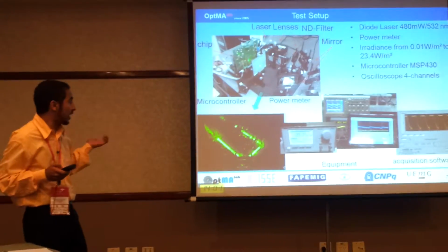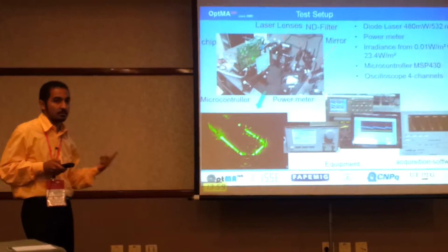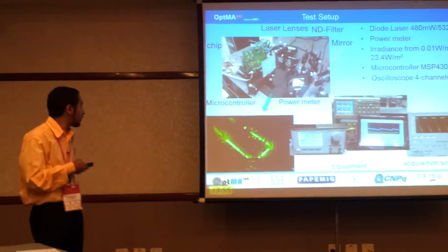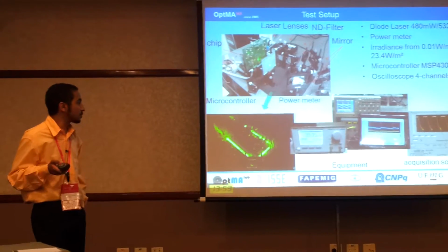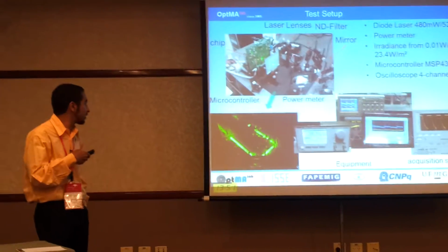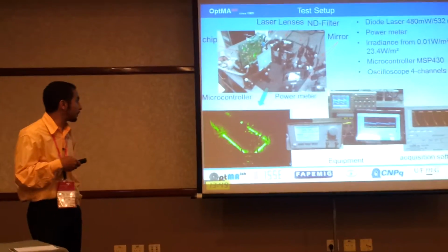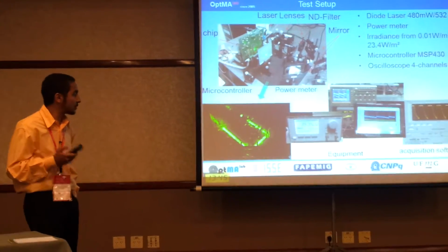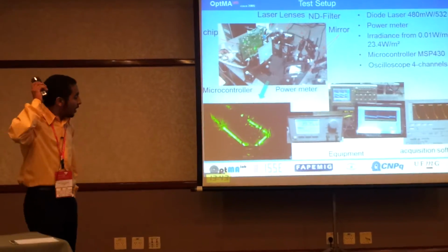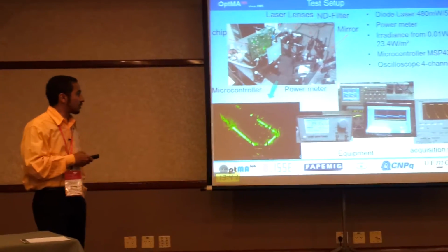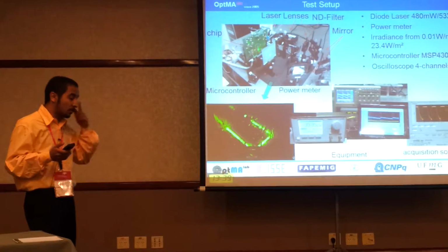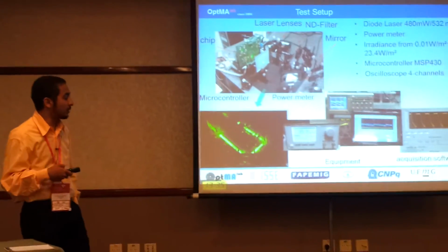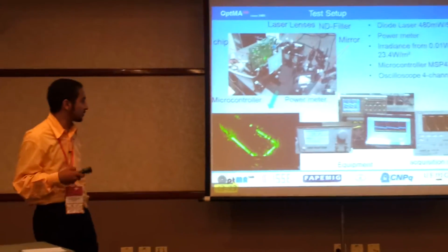The control signals, such as reset, PS and TX, were generated by a microcontroller, and the response of this circuit is read on the out node by an oscilloscope connected to a computer. The data from the oscilloscope were acquired with acquisition software programmed by us for this application.